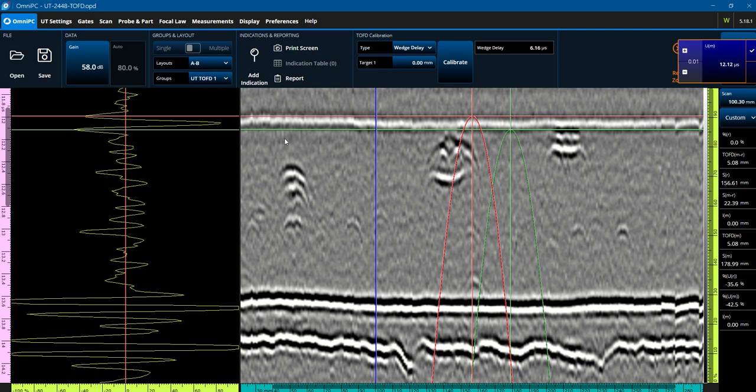And now also, if I move this cursor to, let's say, around the first positive cycle of my back wall, you notice that the distance between these two is read to be 18.95, which again is very close to BeamTool's estimation of 0.9 millimeter of dead zone from a 19.5 millimeter plate.